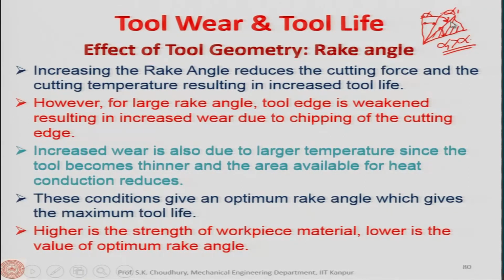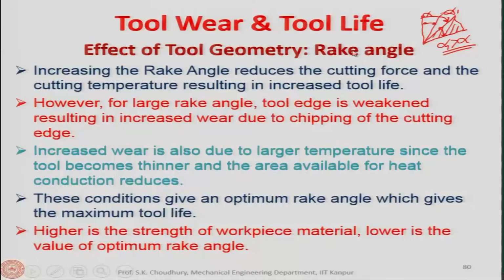and this will result in the increased tool wear, because it may break, it may chip in and so on of the cutting edge, because it is weak. It may even result in the mechanical breakage of the cutting edge. Okay. So, therefore, we cannot really infinitely increase the alpha, although the increase in the rake angle resulted overall in the increased tool life, okay. But to some extent, because at a larger rake angle again the tool life will be less.